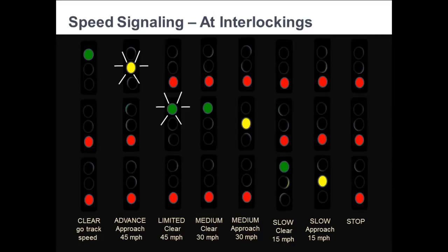The turnout sizes are commensurate with their use. In some areas on the East Coast, the railroad network is highly complex with over 600 trains per day, 4 to 6 main line tracks with crossovers and branch lines heading everywhere. In situations like this, speed signaling is essential. With speed signaling, signal aspects exist for each turnout.